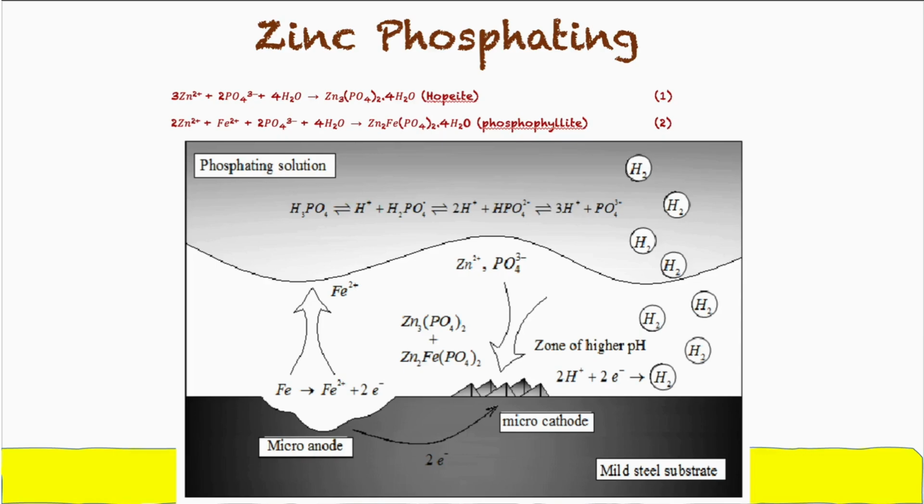When water vapor permeates through a coating film applied over the soluble salts, blisters can form. Rinsing helps in removing loosely adhered crystals, but the last rinse should contain a low concentration of chromic acid so that we can protect against corrosion. One thing to mention here: due to the toxicity of chromium 6, which has proved to be carcinogenic, the chromate rinse has been replaced.